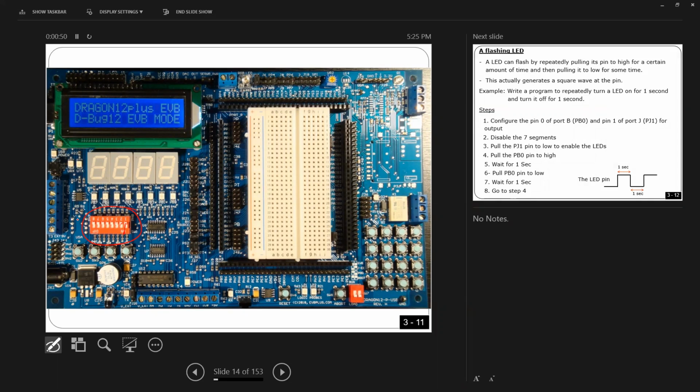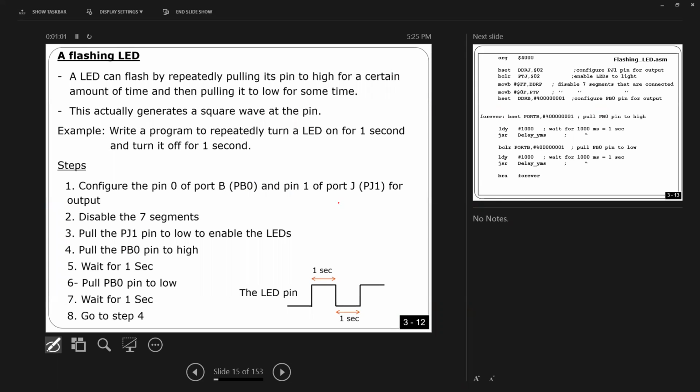So first of all, this is connected to port H, okay? And the way it is designed, as you will see right now, if this is port H, this is PTH, this is the pin, right? PT0, for example, or PH0, okay? The way it is designed, if the switch is connected, so I have a circuit here, it's going to put 0 volt here, right? And if the switch is open, I can have 5 volt here. So I have a small circuit. This small circuit is going to put 0 volt or 5 volt. Is that okay? It's a very small circuit. You will see it right now.